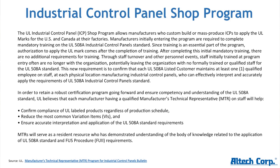UL recognized is not equal to UL recognized. Applying a component in its intended application is one thing. Just applying a component randomly might negate the UL approval. So you really have to be careful. That's why the 508A standard is 200 pages long. So there's a lot to go by, but it's worth it at the end, because you have a safe and UL conform panel.